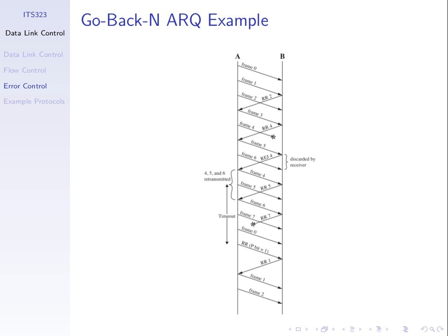It doesn't have to be that. We could ARQ every 1 frame, every 3 frames. It's up to the receiver when to ARQ. We could have sent an ARQ here. We could have done that. Yep. Without requesting. But it may not have helped in this case, because if we sent an ARQ here, if we timed out from the previous one, we'd still send the ARQ request, because we've timed out. So it'll discard the first ARQ.